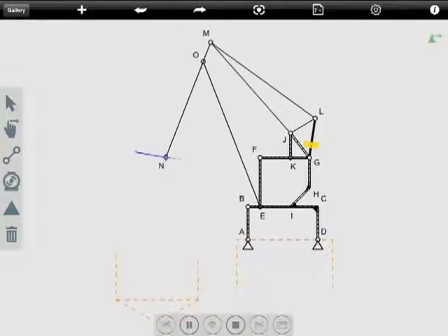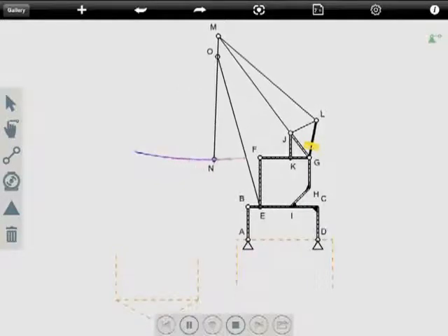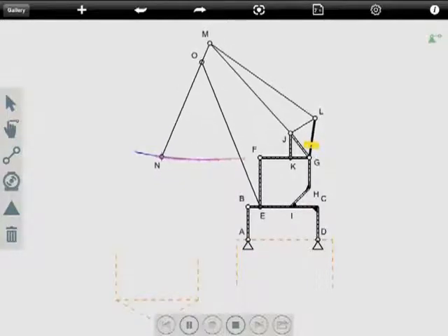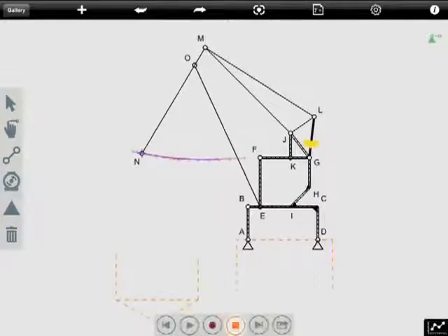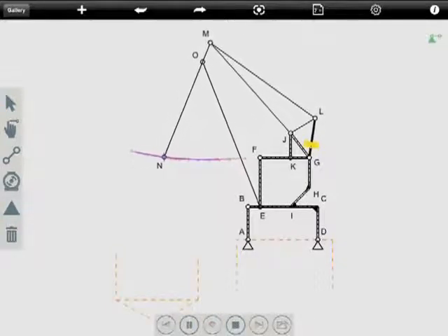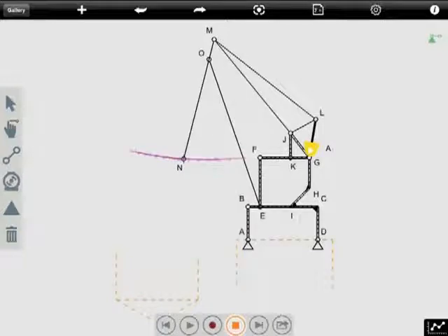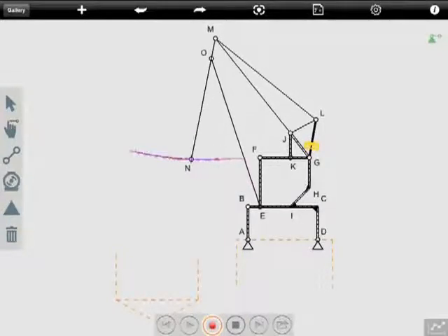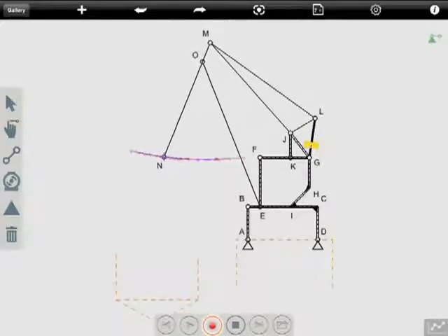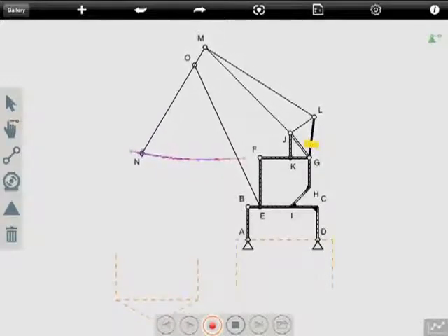The play toolbar now displays at the bottom of the window. You can pause your animations, and stop will move the animation to its home position. You can also tap record to record your animation. Recorded animations are available in the report and inside your photo library. You must first record the animation before it will be available in the HTML report.